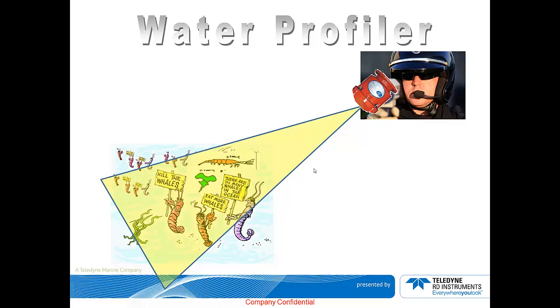And just like bottom tracking, water profiling also uses some parameters to determine whether a return signal is good or must be rejected. These are the WA parameter and the WC parameter. The WA command is the fish rejection threshold.